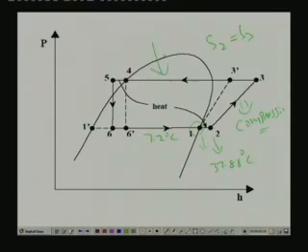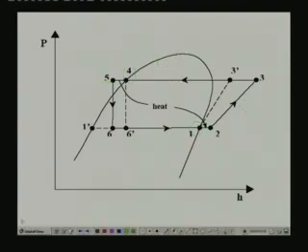This is the condenser, as you know, and we know that point 4 is a saturated liquid condition at condenser pressure, and the condenser is operating at a temperature of 54.4 degrees centigrade. So, we can find out the condenser pressure. Point 4 is a saturated liquid at this pressure, so we can find out the properties at this point. And 4 to 5 is what is happening in the liquid suction heat exchanger, and as you can see, during the process 4 to 5, the hot refrigerant liquid loses heat to the cold vapor. So, there is a heat transfer in this manner.